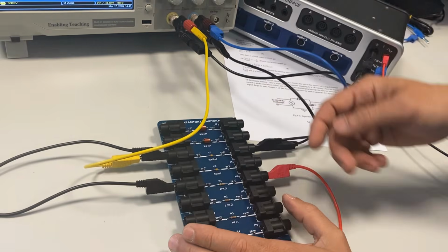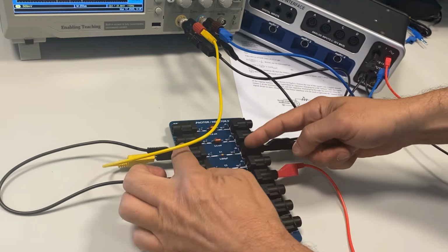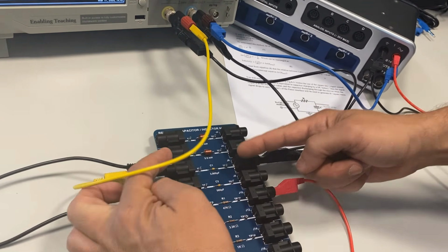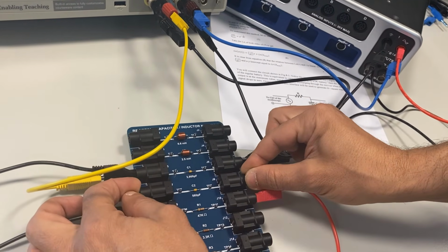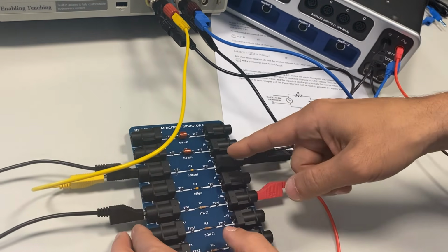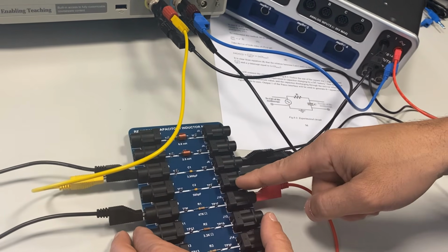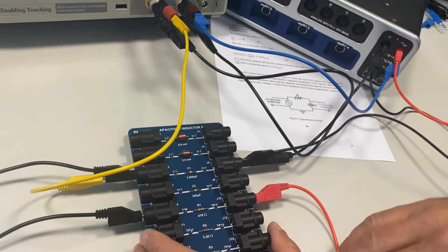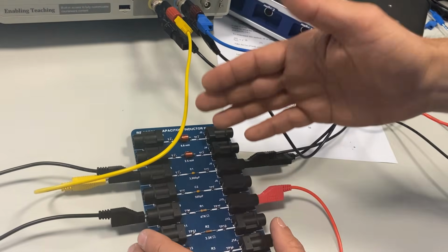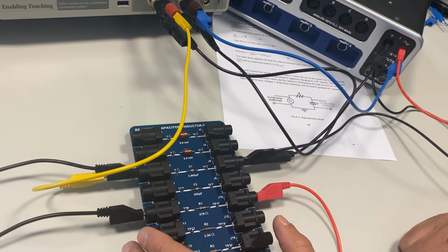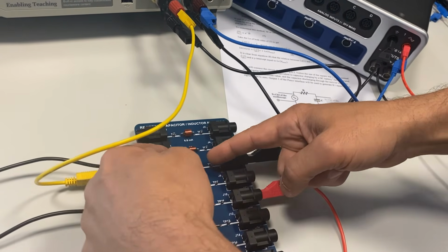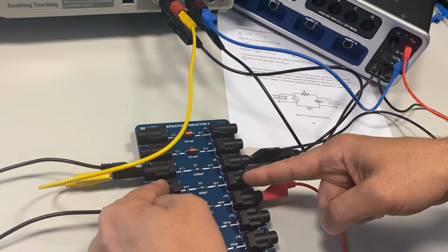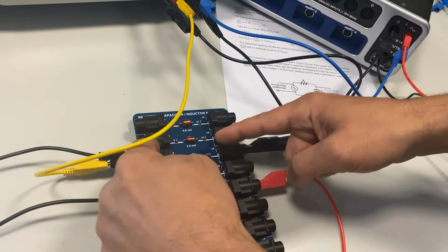Now notice that for parts 2 and 3, we have to switch between C1 to C2. So we'll have to remove these two wires and insert them in C2. And then after that, we connect C1 and C2 in series, and we will show you a picture of that connection. And also, finally, we will connect them in parallel. Parallel connection is very simple. You just take two wires from C1 and connect them to C2, just like this, two wires, okay?